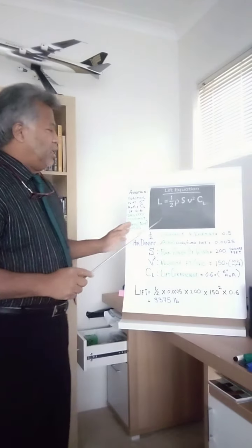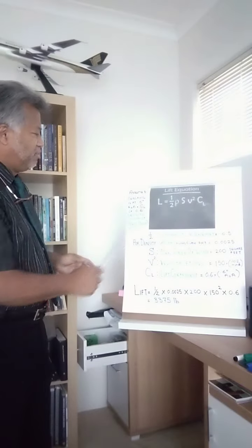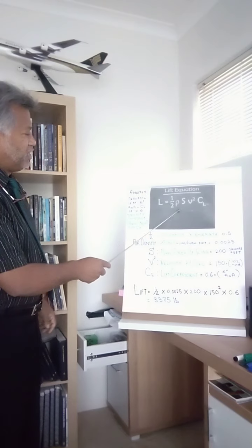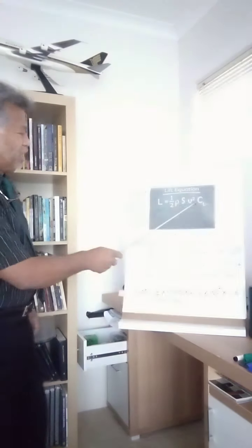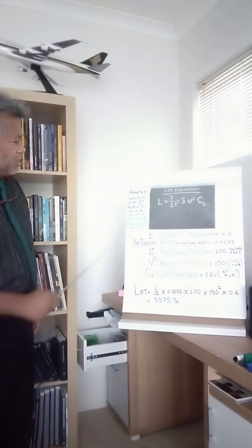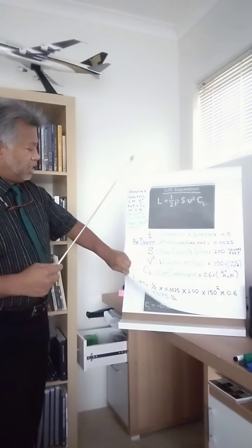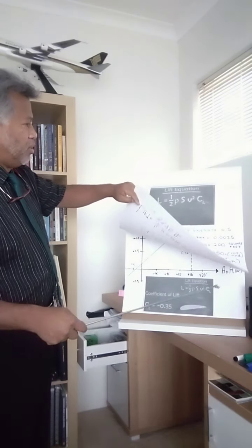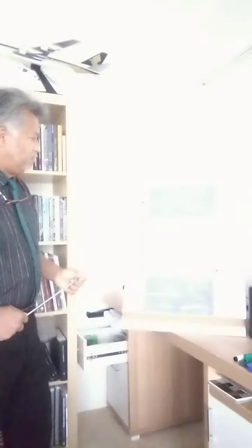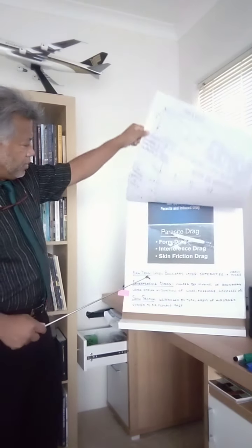That way it's easy to explain the coefficient of lift based on this lift equation. Basically, the basic lift equation is half of the density, surface area of the wing, velocity of air squared, with the coefficient of lift. Okay, so these are the numbers that have been crunched. We can go into detail, but rather than that, we need to carry on further with the understanding of the coefficient of lift. Before we do that, we can go and talk about drag.